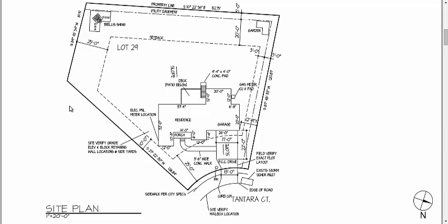And then within that lot, now we're going to locate where our house is going to be. Now this is very important, often overlooked and certainly not understood a lot of times: you can't build anywhere you want inside this lot. Usually the city has codes or guidelines to tell you where on that lot you can build. Now these are called either easements or setbacks. You see the word setback right here.